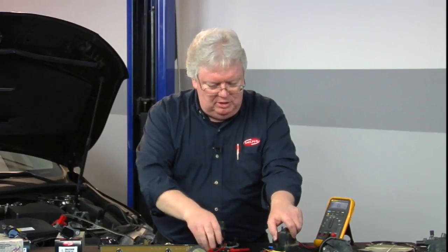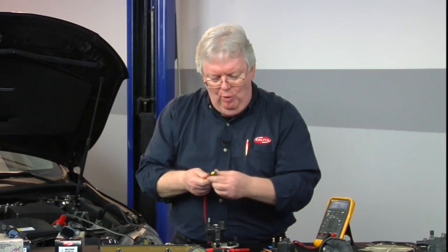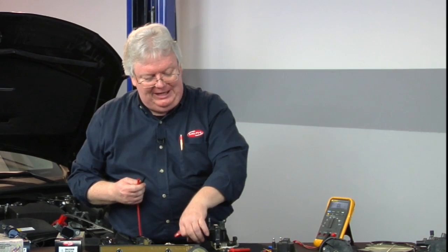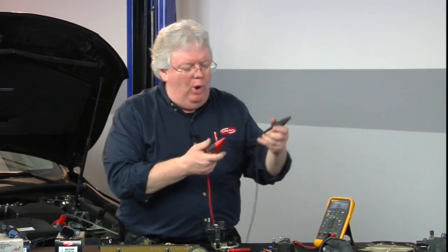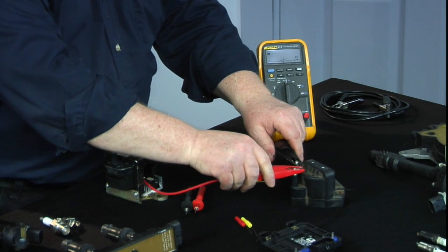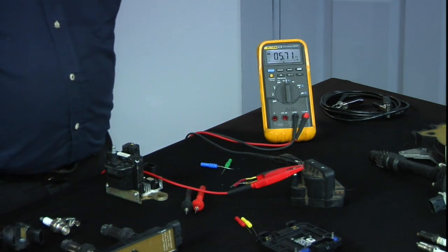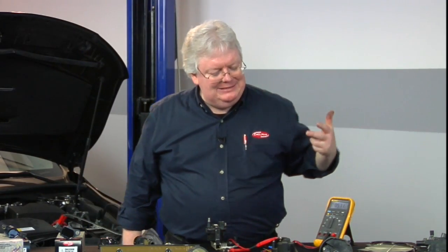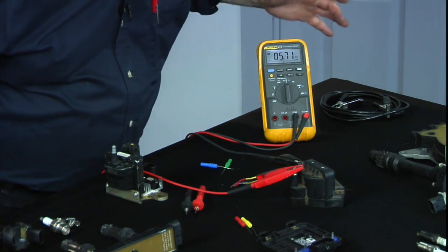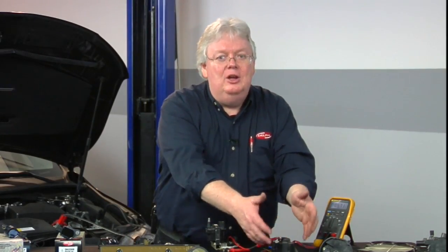And we can also measure the secondary winding resistance to see if we have an open. Remember, it may still fire, but it would probably break down under a load because we have one more spark gap actually in the coil. And that can sometimes cause carbon tracking, both internally, which you can only see under a load when it starts breaking down, or externally. You may be able to see some telltale signs of that. And we are seeing about 5,000 ohms. So that's the secondary winding resistance.